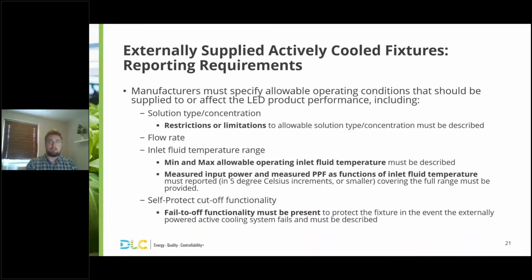All right, so some reporting requirements for these actively cooled fixtures. Manufacturers have to specify the allowable operating conditions that should be supplied to or affect the LED product performance, including the solution type and concentration. Restrictions or limitations to these solution types or concentrations must be described as part of the application process, either in the spec sheet or some kind of marketing materials, and that information will be reported on the QPL. Also, flow rate must be reported in gallons per minute.